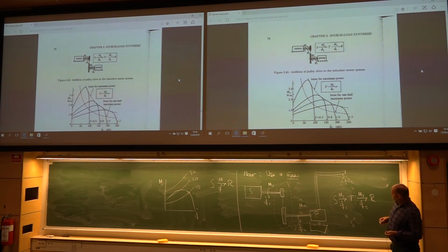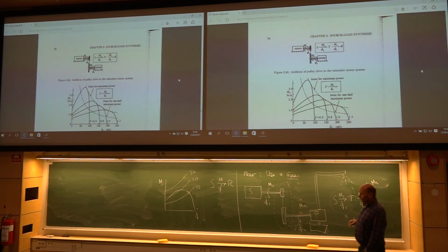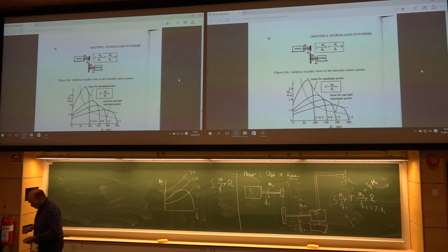Well, what was the coupling here? For a transformer, this phi dot number 2 was equal to the transformer ratio T multiplied with flow number 1. While this one must now be 1 over T multiplied with torque number 1. So this is just taken from the definition of a transformer.